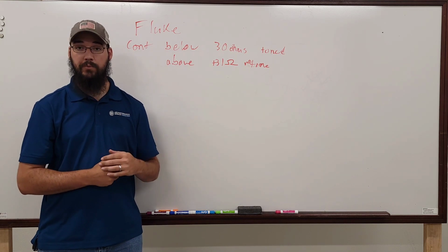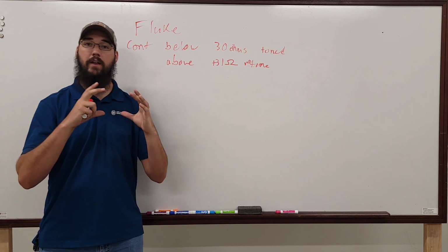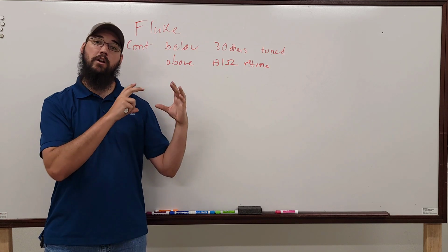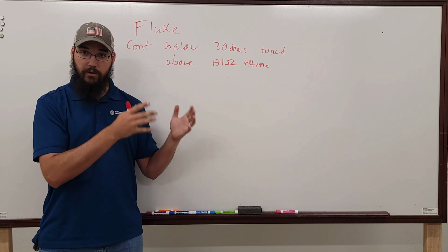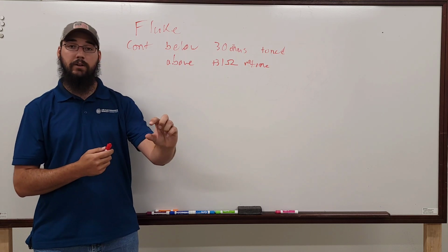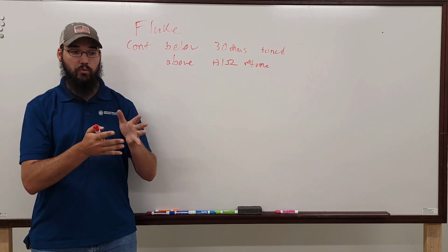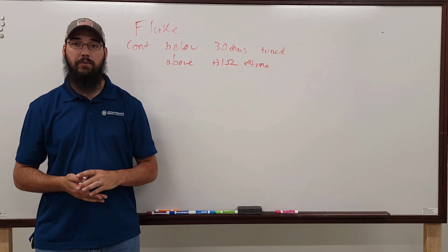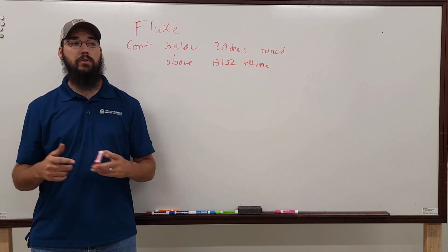So 20 ohms is going to show 0 ohms at millions of ohms range and thousands of ohms range. But in hundreds of ohms range, it's going to show 20 ohms. So it's very critical that we're paying attention to that, and that we're reading what the indicator says, first of all. And two, we're using it properly. If you want to use manual range, fine, that's okay, but use it properly.